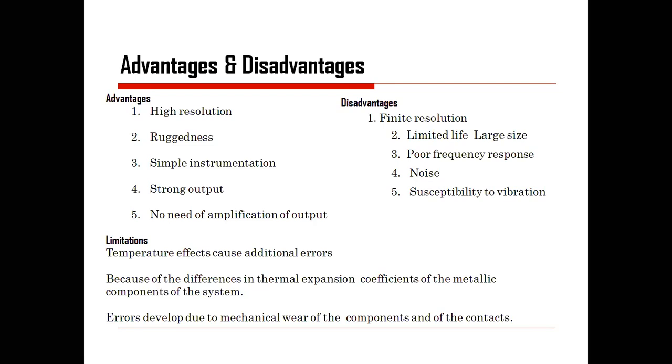Then there is sensitivity to vibrations. Actually, we have used a spring, and we have seen some accelerometers, so damping action may take place. As there is a spring, if we mount it in a noisy or vibrating environment, this vibration may lead to movement of the spring, and due to the movement of the spring the connecting rod will move, which will change the resistance, causing a voltage change. So a false output may be generated. So we have to take care with this system or such a type of